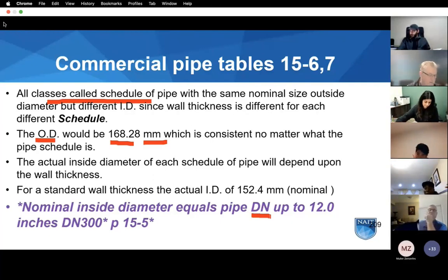So if we have pipe that's 150 millimeters, we can call that a 6-inch pipe. If we jump down to 8-inch and then look across, you can see you have numbers for schedule 20, schedule 30, standard wall. Thickness is 8.18 millimeters, and then the number there, 42.2. If you look at the note at the bottom of the page, that's the kilograms per meter of 6-inch standard wall or schedule 40 pipe.